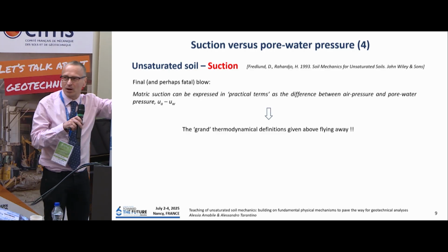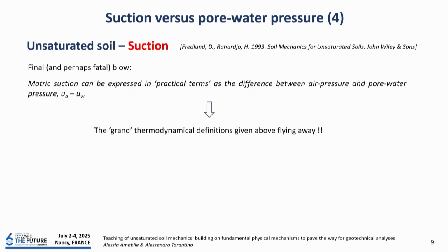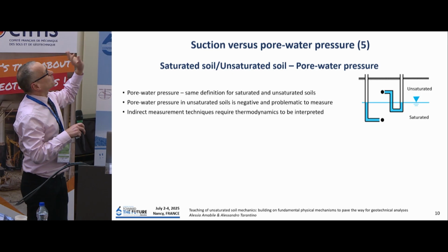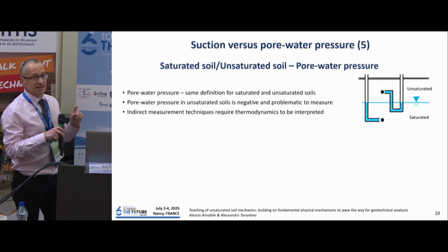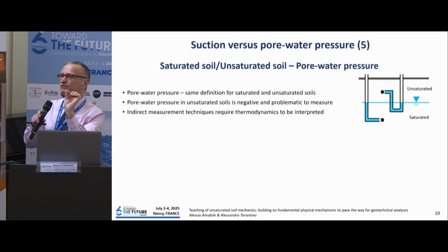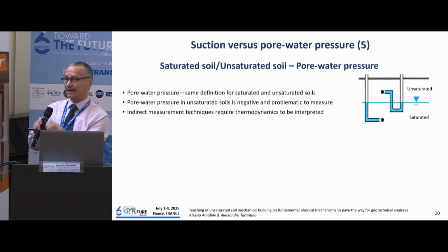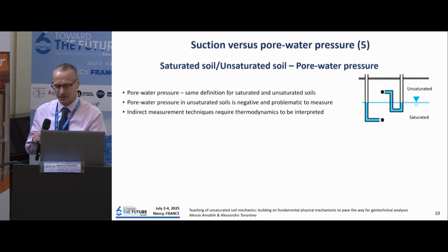Finally, at some point, you read and you say, oh, in practical terms, that's the difference between air and water pressure. So the ground thermodynamical definition, poof, disappearing. So what? Let's clear the ground first, immediately. Pore water pressure is defined exactly in the same way in saturated and unsaturated. There is one difference, and the difference is that in unsaturated the pressure is negative, and then it is more difficult to measure. Because it is difficult to measure, we have devised indirect techniques, and this is where you need the thermodynamics to interpret the technique, but that's clearly another story.